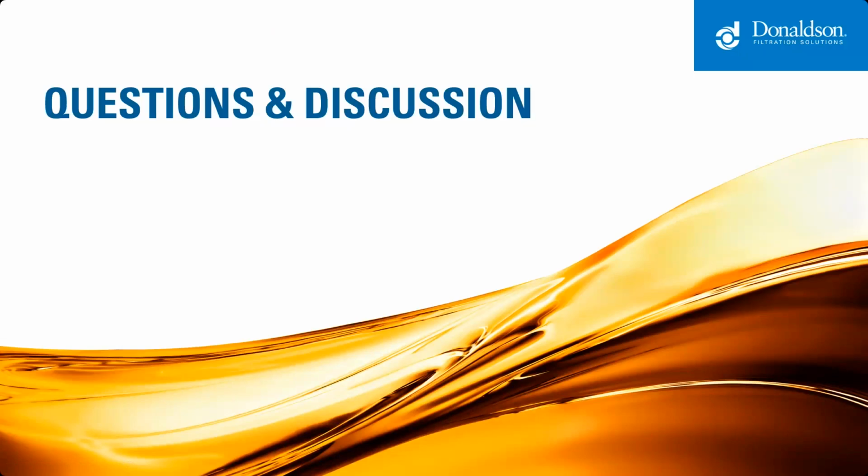Yeah, good question. So when adding offline filtration, let's take the example of a permanent installation. We're going to put a panel on there and it's going to run 24/7. It's going to do a couple things. First off, it's going to take that pressure off of the inline filtration that's there for the normal working circuit. So say you were having to replace those filters every 500 hours and they're being loaded really fast, that offline filtration is going to add more surface area to that circuit and take that work off of those filters. You might be able to extend the actual replacement of the filtration with the normal working circuit.